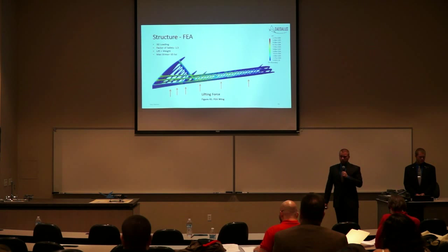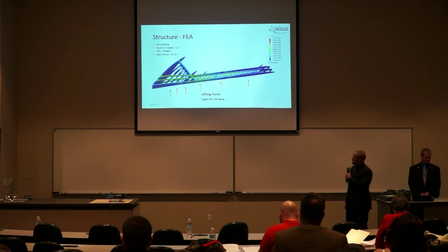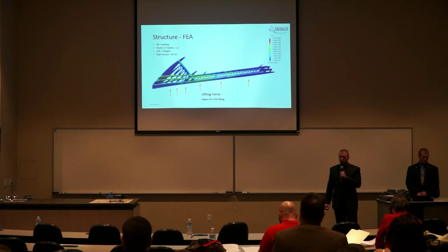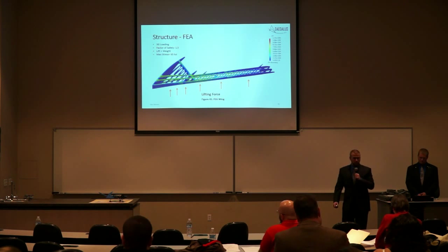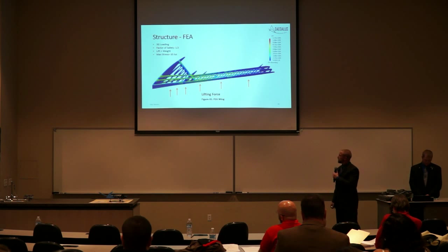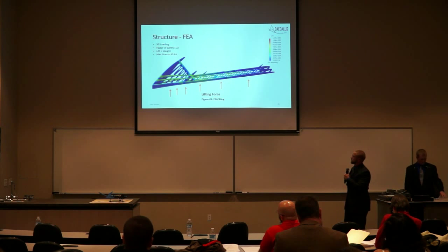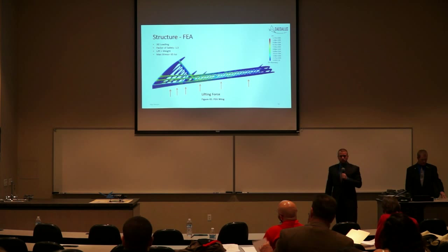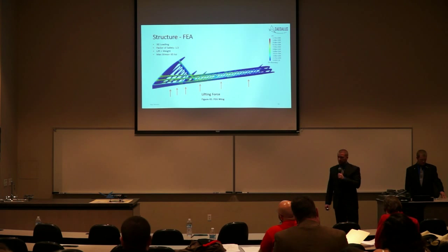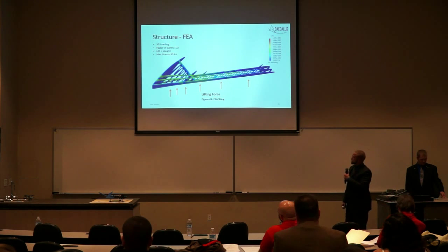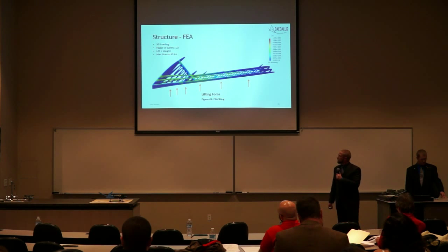Similar calculations were performed on the wing. The loads seen were used by our lift distribution, pulled from Schrenk's approximation, which was calculated during the course of the semester. Again, a 3G loading was applied, as well as a 1.5 factor of safety. You can see that, again, assuming lift equals weight, our max stress is about 65 KSI, which is still below our 76 KSI limit.